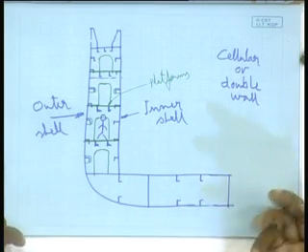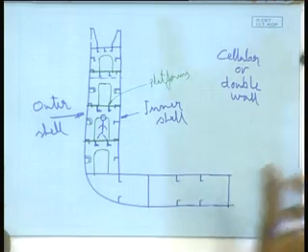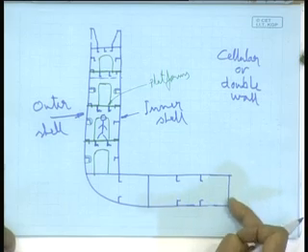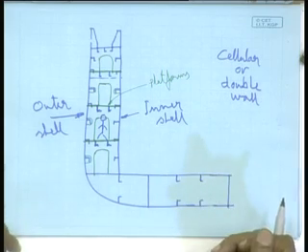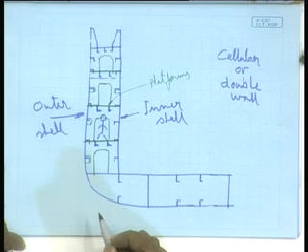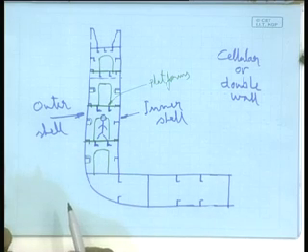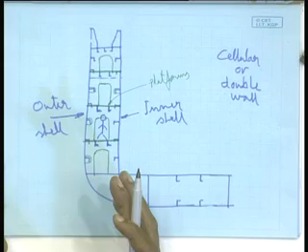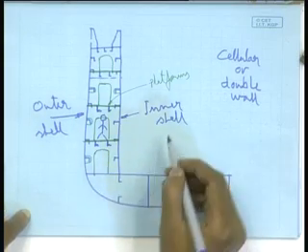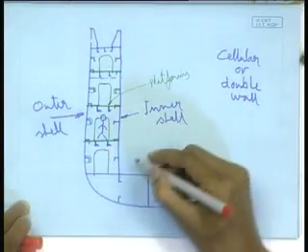Both are the same, but you have some functional advantage in a duct keel. So, you can have a duct keel arrangement or a center girder arrangement, that depends on the designer. So, this is what is a cellular or double wall construction, which provides the required torsional strength. And here is another advantage you can see: you have the cargo space, the so-called container loading